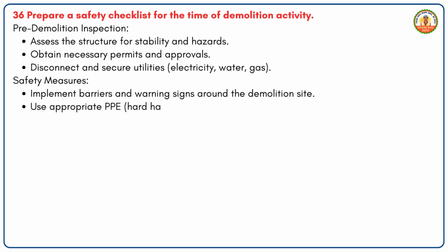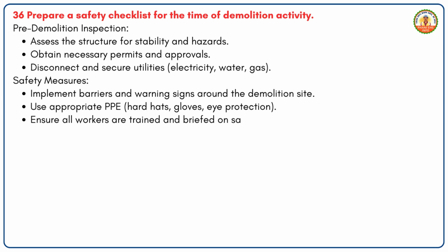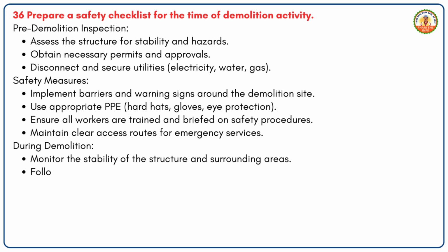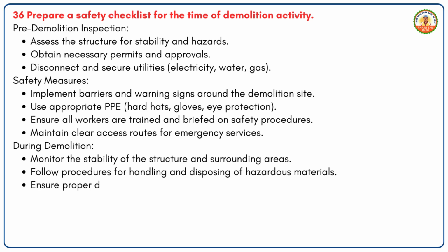Use appropriate PPE, hard hats, gloves, eye protection. Ensure all workers are trained and briefed on safety procedures. Maintain clear access routes for emergency services. During demolition, monitor the stability of the structure and surrounding areas. Follow procedures for handling and disposing of hazardous materials. Ensure proper dust and noise control measures.